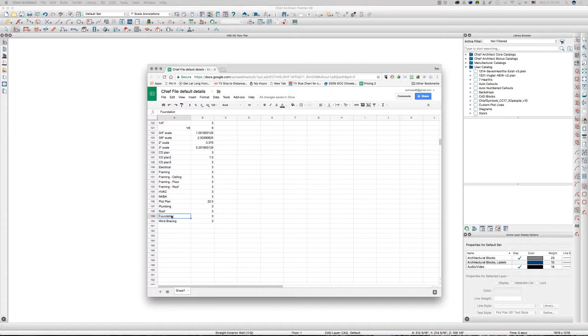Sometimes you might have a slab on grade, like a walkout basement type of thing, and so I need to show the foundation that comes up to the slab, but then in my CD plan on level 0, I would show the wood framing up layer.